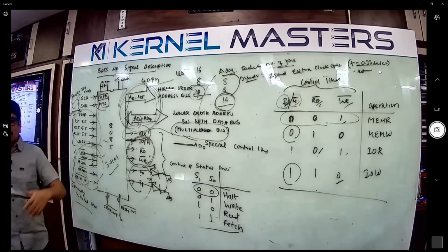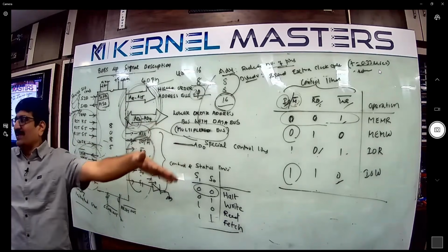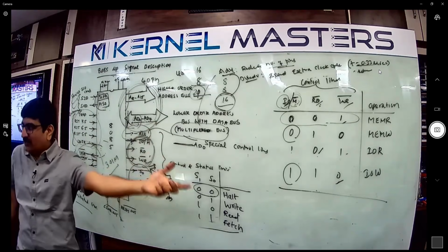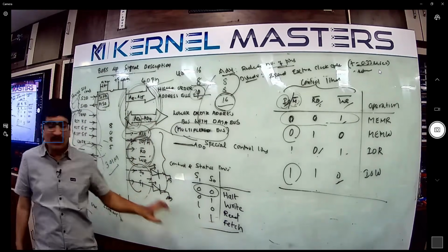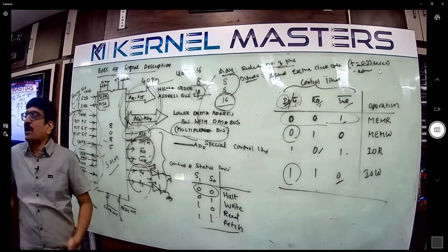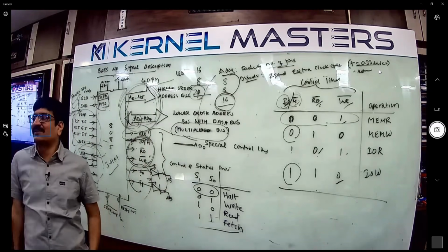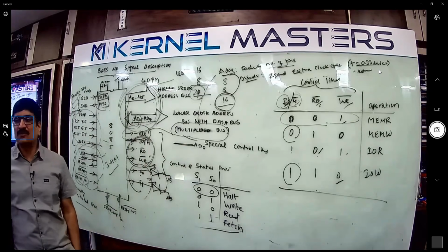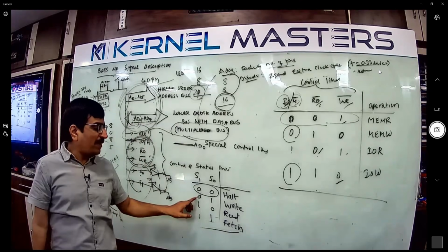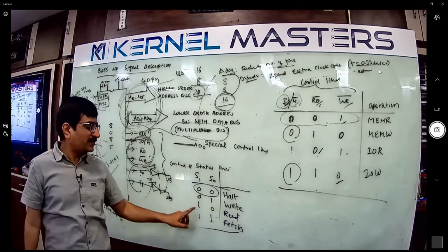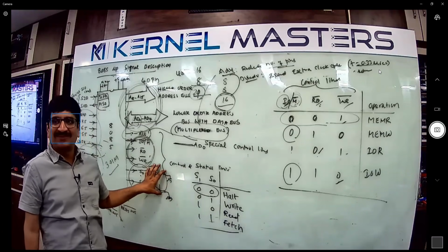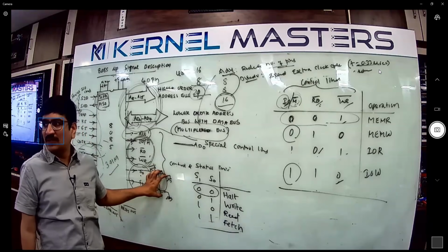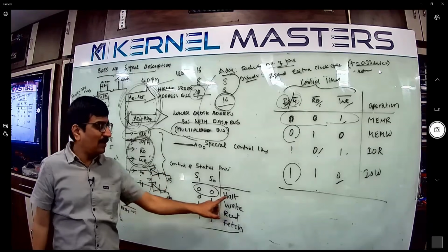Say the microprocessor executes MOV A, B. What is the first step? Fetch. Fetch means both are on, and we understand the microprocessor just loaded the instruction. Normal write operation is 0, 1. Read operation is 1, 0. If no LEDs are blinking, it is a dangerous situation. Something must blink; if nothing is blinking, what happened? Halt.